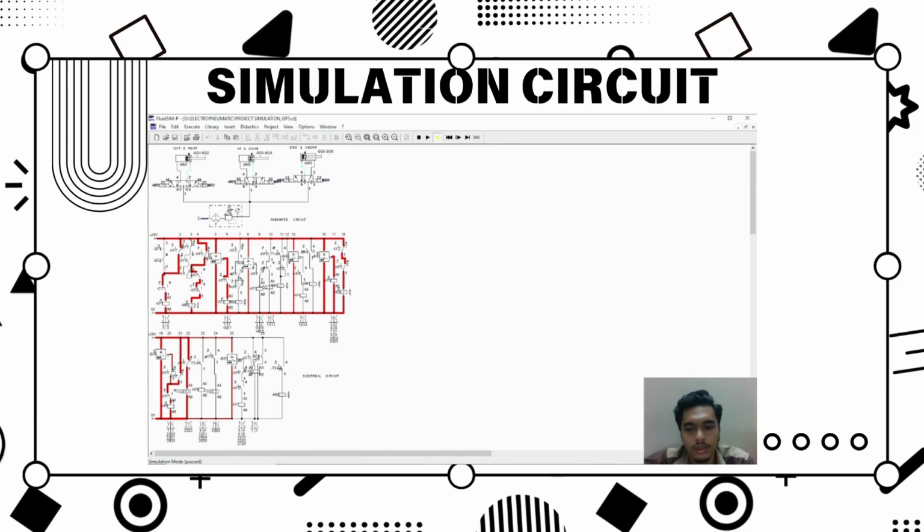And relay contact -KF6 will close and make a latching on for -KF6 here. And relay contact -KF6 will close and activate the timer -T2 for 3 seconds.